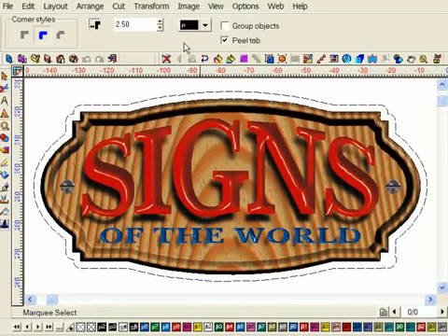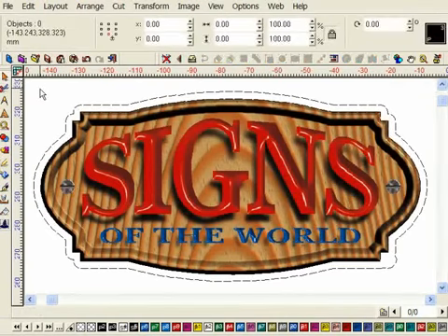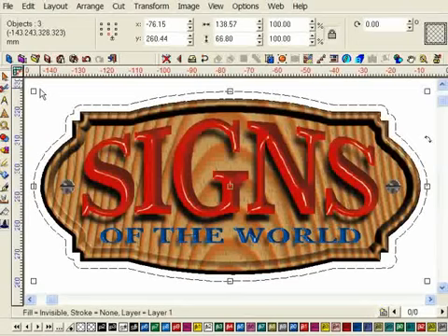Okay, so that's my settings complete for the half cut path, so I will now click to a blank area of my Synapse screen to exit, and my file is now ready to send to the Print and Cut Manager for production. Shortly I'll finish this example and show you the final steps required to complete the job, but first I'll show you some other options.